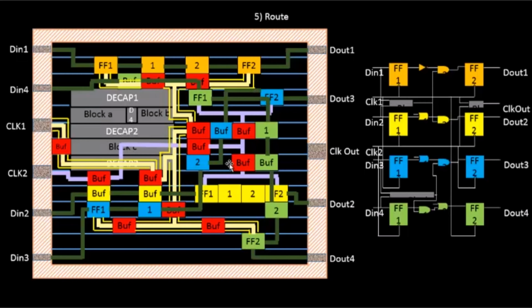Okay, so we'll talk a lot about route in the upcoming sections, where that section is completely dedicated to route. This is the overview of it. Next step after the route is to clean up the DRCs. DRC stands for design rule checks. For example, while routing, we see some placement, spacing issues or shorts.